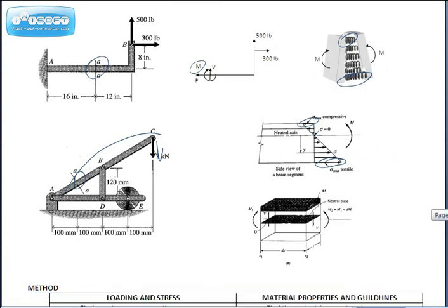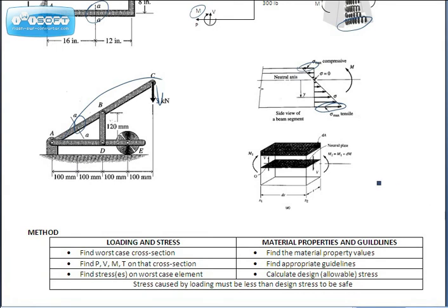In addition to the bending, the material responds. Notice as this bending moment pushes on those fibers, on the top of that cross section, it tends to push that top slice off, which tends to cause a shear in that material.